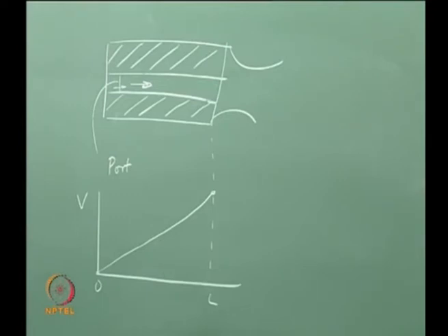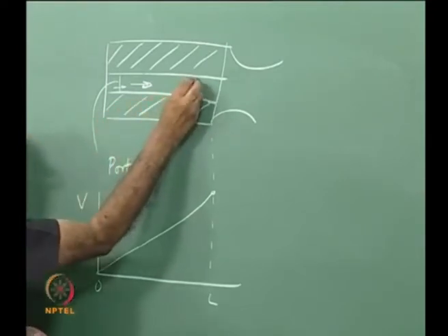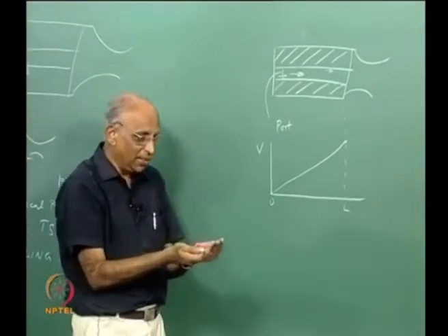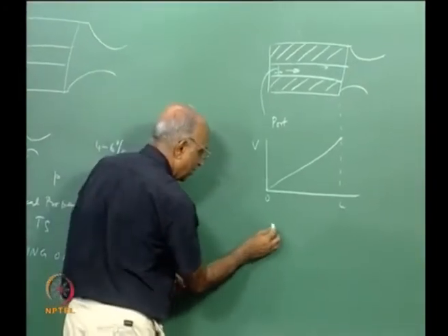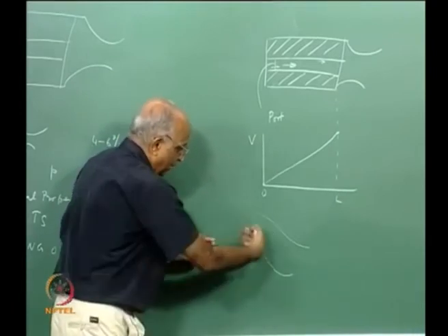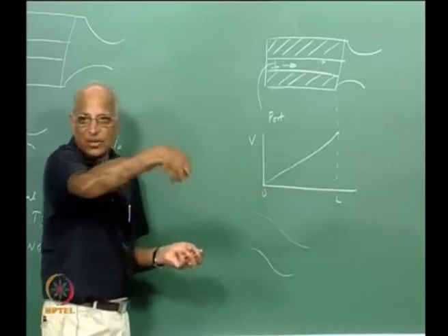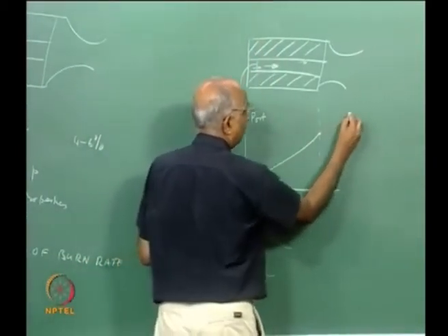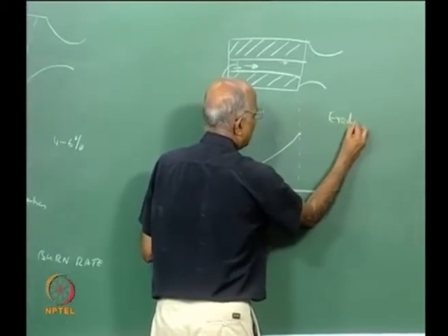Now what does velocity do to a surface which is burning? Well, it can erode the surface, like in a river. Let us say a river is flowing, and what does the current of velocity do? It drags the sand from the river. So also I could have something like erosion, let us write it down. It could erode the propellant surface.